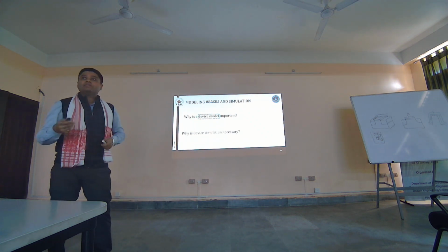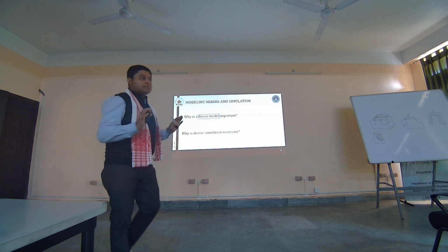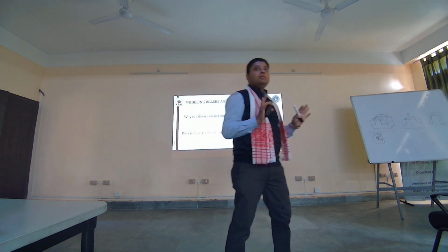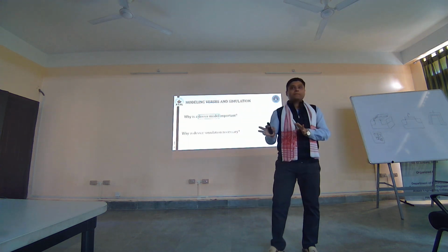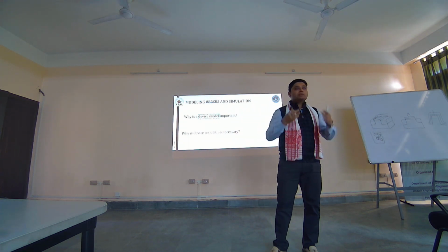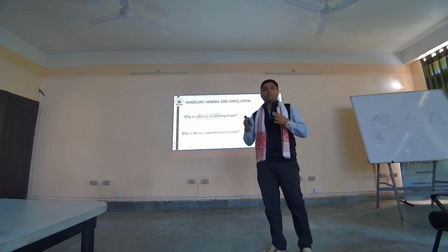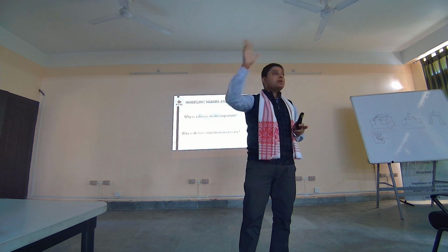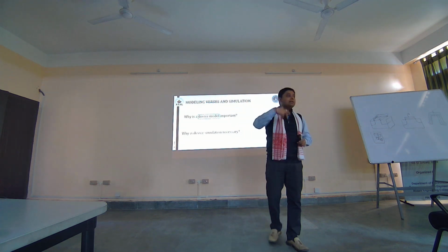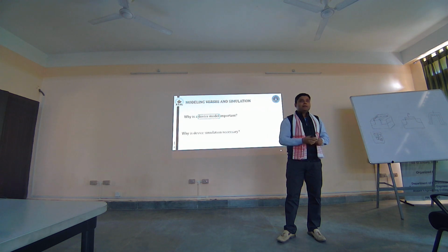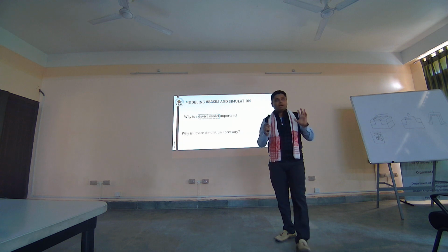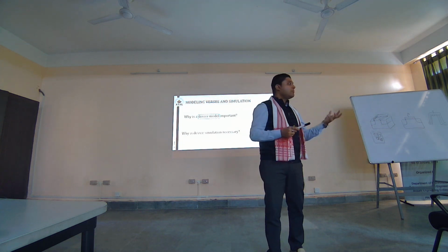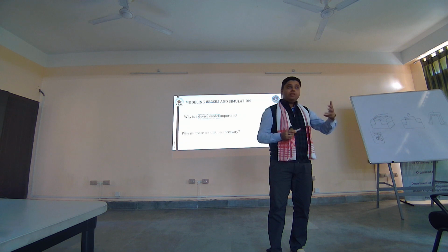Then why is device simulation necessary? Now see, suppose I have developed my model, I equal to M into V plus C, okay. Now, if you ask me at a voltage of 3 volts, what will be my current, right? Earlier I would have calculated it, but now I will use a computing system and then I'll tell you. Now just try to look at it at an advanced level, okay. Now you have a device which is complex in nature. Take for example a MOSFET or a field effect transistor, where you can give your drain current based on the equation which you have, right?